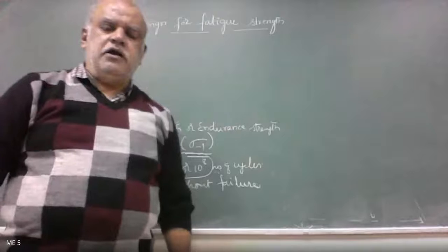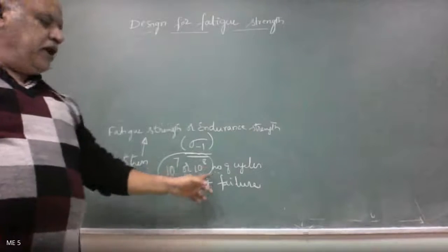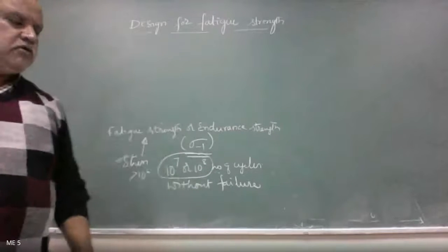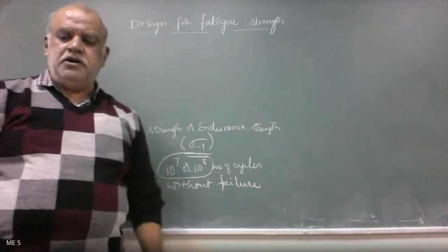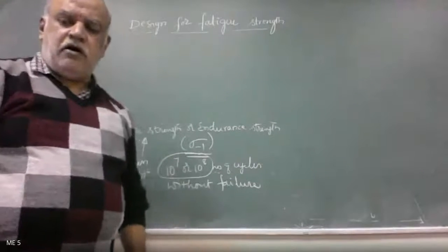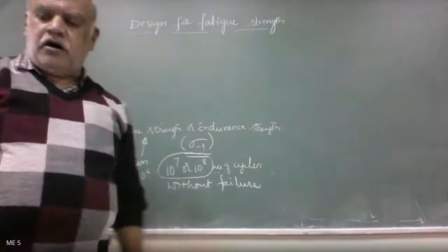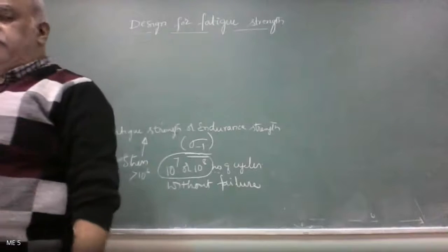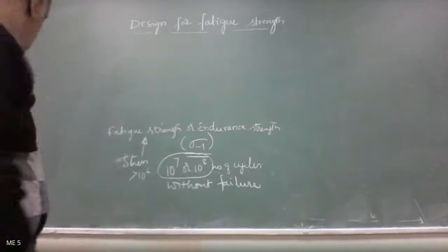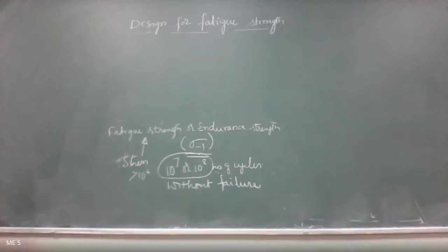It is defined as the maximum stress which a plain specimen can sustain for 10 power 7 or 10 power 8 number of cycles without failure. Please take down. That is called fatigue stress.